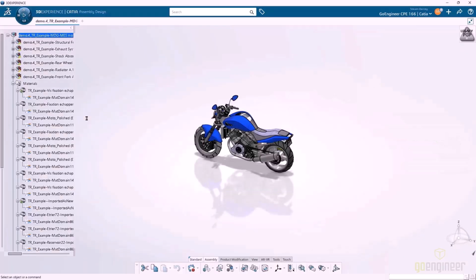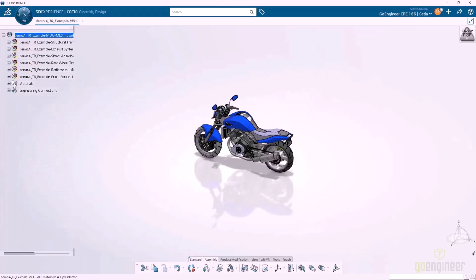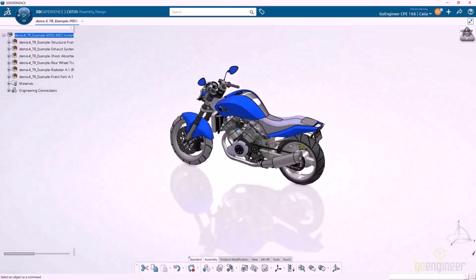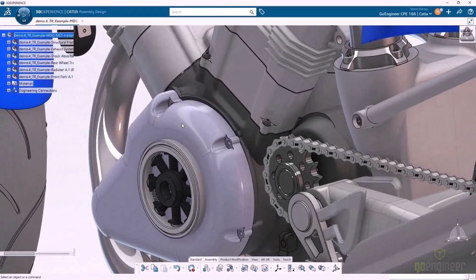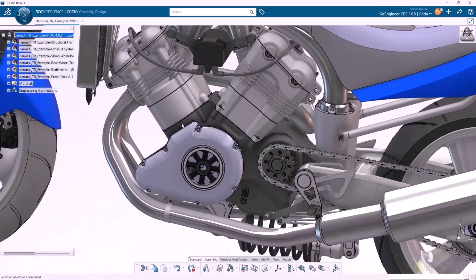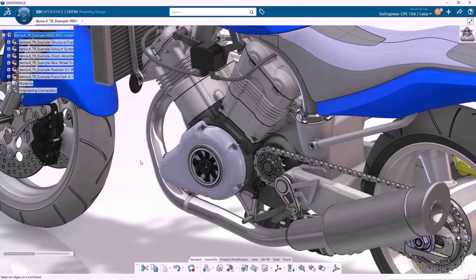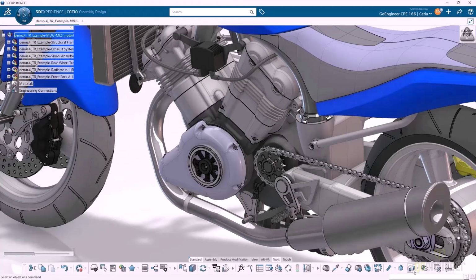So it's going to open that up in CATIA. We'll give that a minute. I don't know a whole lot about CATIA, but I do know how to do a section view and also use the measure tool. Let's zoom in there. I can really see that interference pretty easily. I'm going to go over to the Tools tab and do section view.